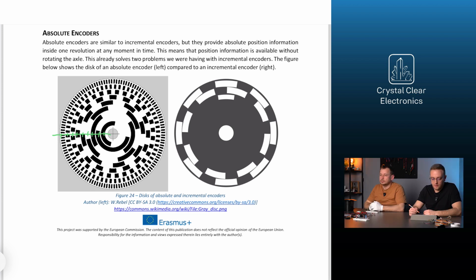In the figure, the outermost ring represents the lowest bit and the innermost ring represents the highest bit. It means that the smallest detectable rotation is when the outermost ring has a signal level change, while the inner ring will only change after half a turn.